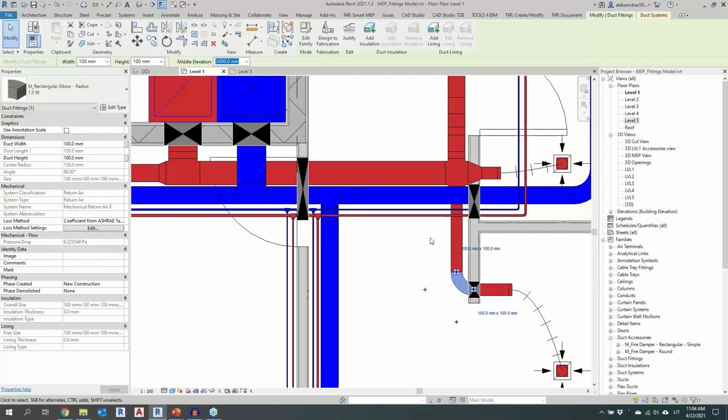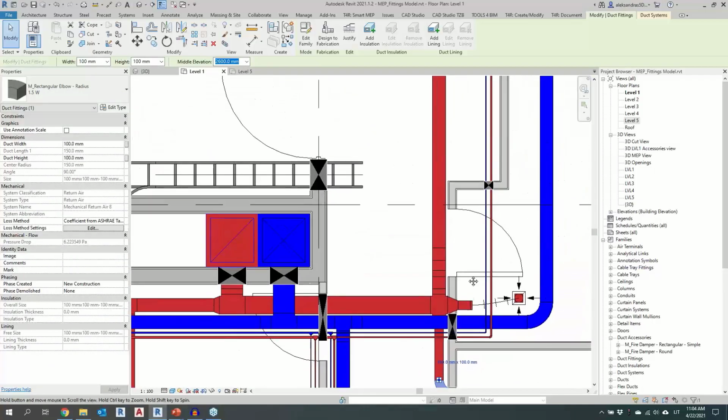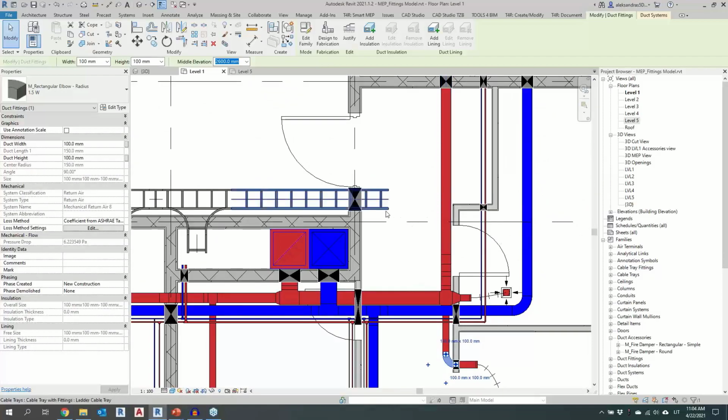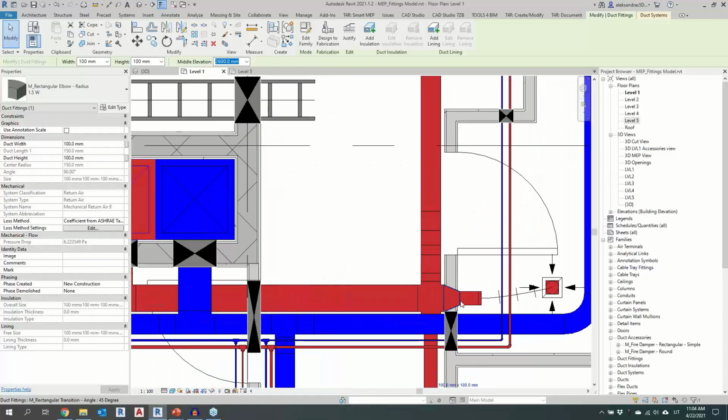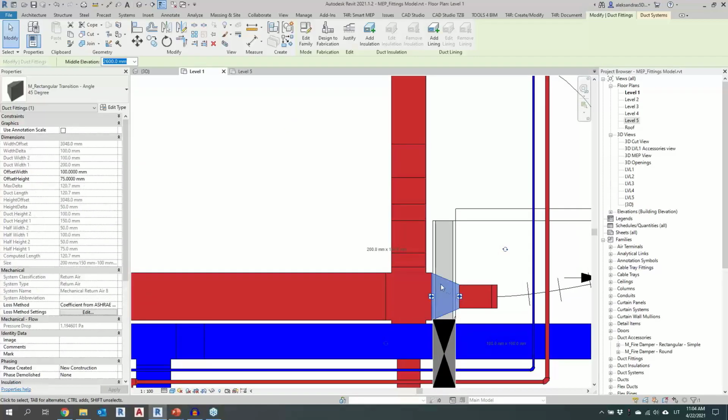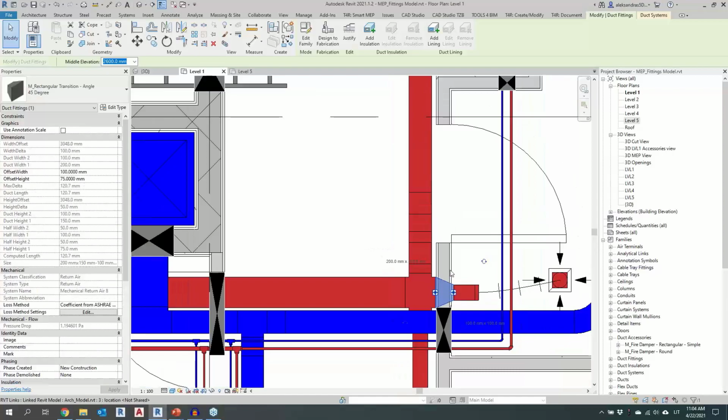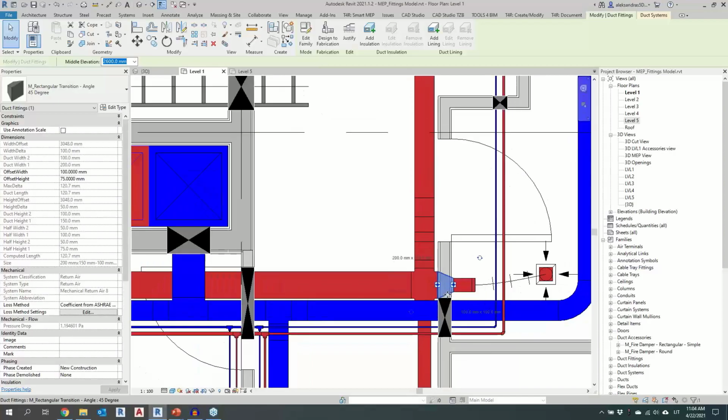It was joining openings, creating openings for all sorts of straight MEP lines, so that being cable trays, conduits, ducts, pipes, and even beams. But for situations like this one, when there's a fitting, somehow it got into the model, we have it and we just have to deal with it. Previously, there was no way to create an opening for such a situation.